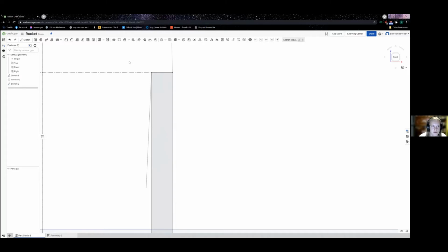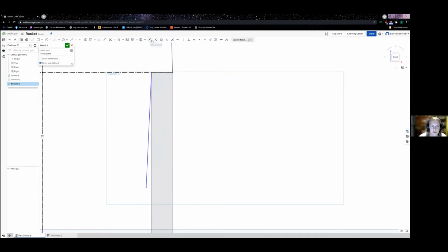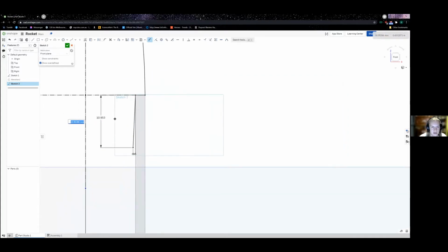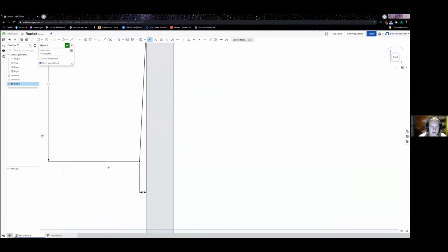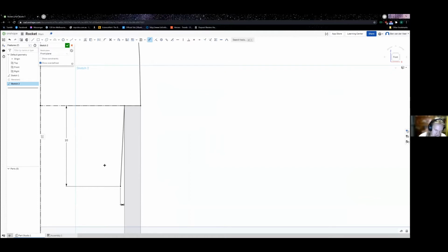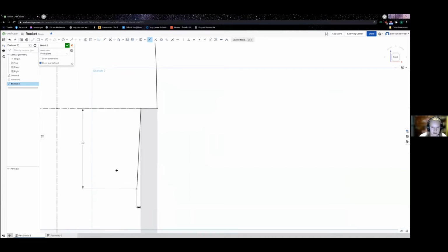So what I'm going to do now is edit the sketch and add some more dimensions. I know that I want the difference here to be 0.5 millimeters approximately. And for the length of this insert, generally 10 to 15 is a good amount. I'll just chuck it at 10. And now thinking back to what I was saying about you wanting a consistent multiple of 0.4 for your 3D printer when you're talking about thicknesses of your parts.